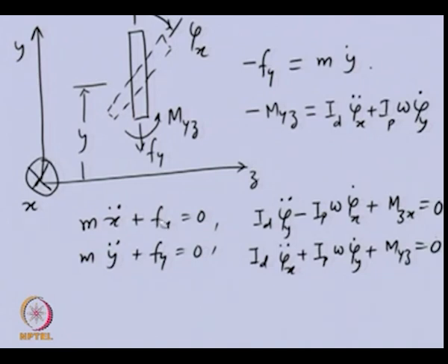Now we need to relate these elastic forces with the shaft displacement, that is linear and angular displacement, through the influence coefficients. So we can relate these forces and moments like this.